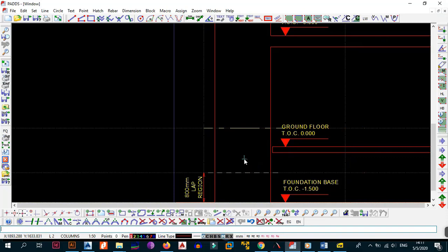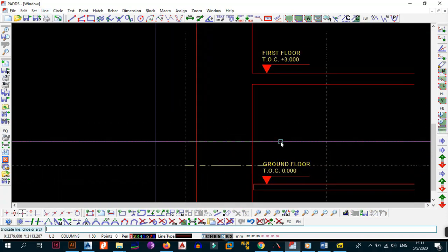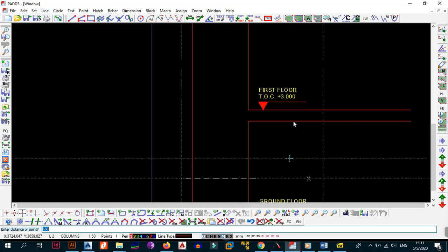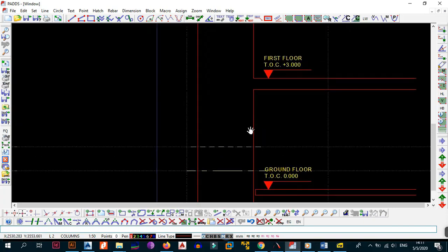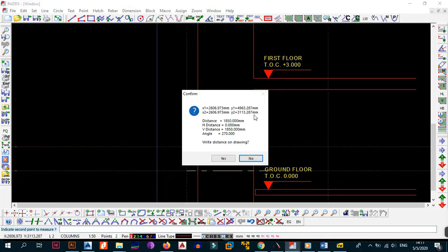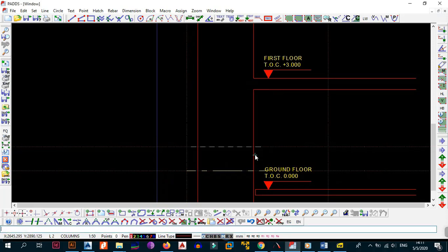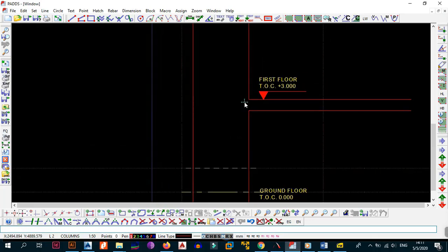So what you're going to do is you're just going to LP this point by 650. Okay, then just B3, copy this line that signifies the lap, then put it there. Then what you do is you're going to say from this point, in this case you would want to cast 2 meters from this point, right? But you understand, look, if you just D2 to check the distance between these 2 points, it's 1.85. And also even if you D2 from this point to this point, it's 2.5. So this is going to be the next cast height for us.